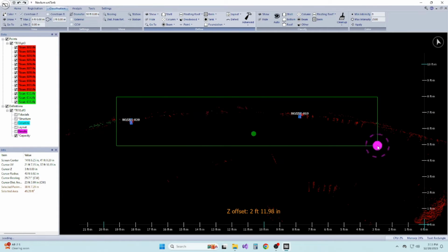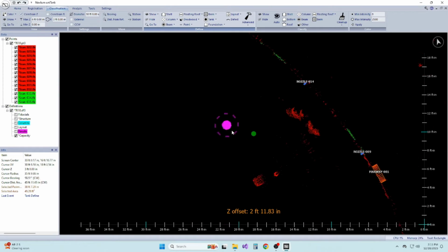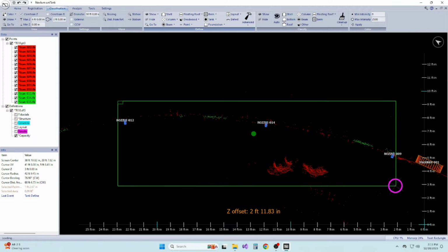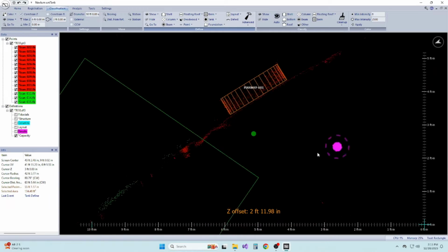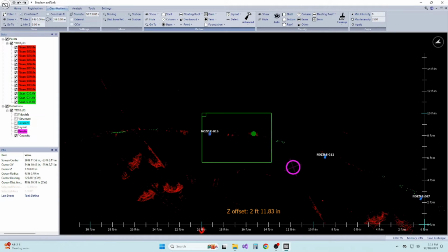As you see in this case, the auto detection has picked up a lot of the floating roof seal hangers. Using the rectangle, polygon, or circle tools, I can draw a shape around the erroneous appurtenances and delete them. I can either use the Delete Selected tool in the Advanced menu, or I can simply use Shift-Delete.